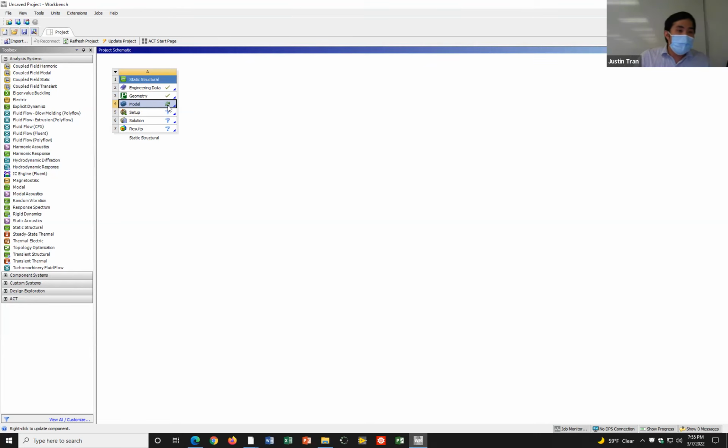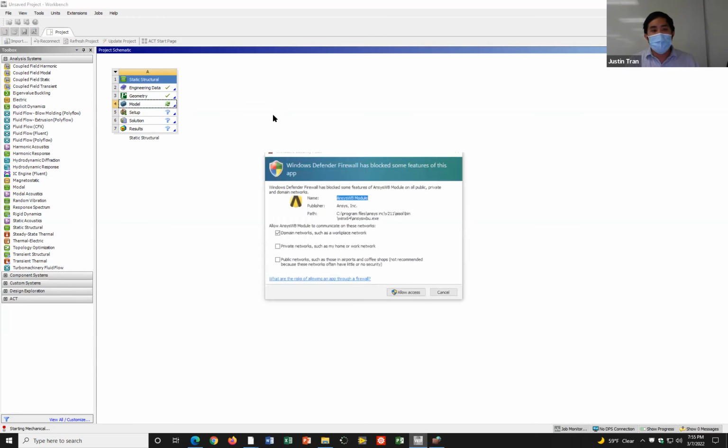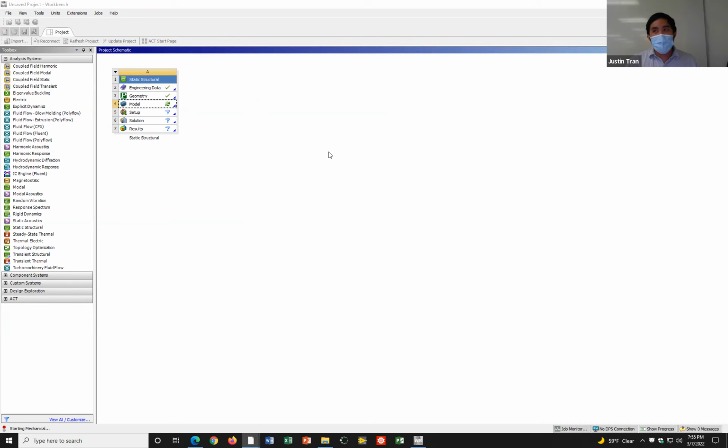Did I do it? No, I didn't. There we go. Okay, and so when you double click on model, it'll open up Ansys Mechanical for you. Okay. And if you're in the lab, you might get a pop-up that says, will you allow it through the firewall? You can just hit cancel and then it'll just be fine.